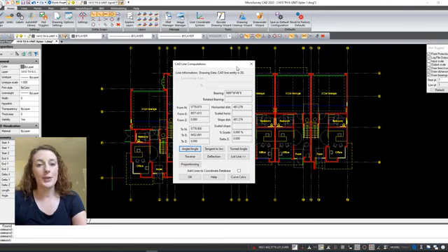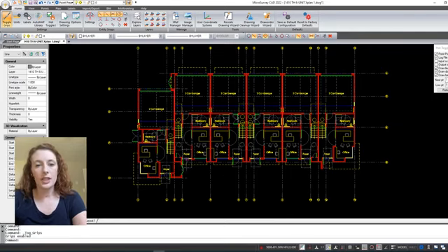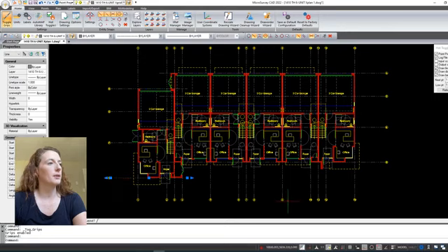How you turn that off is this little button up here called toggle grips. When you turn that on, it gets rid of that line information that pops up, and it acts more like a standard CAD program where you click on the line and you're able to have your grips on either end. So now you can see that each of these grid lines are individual lines.